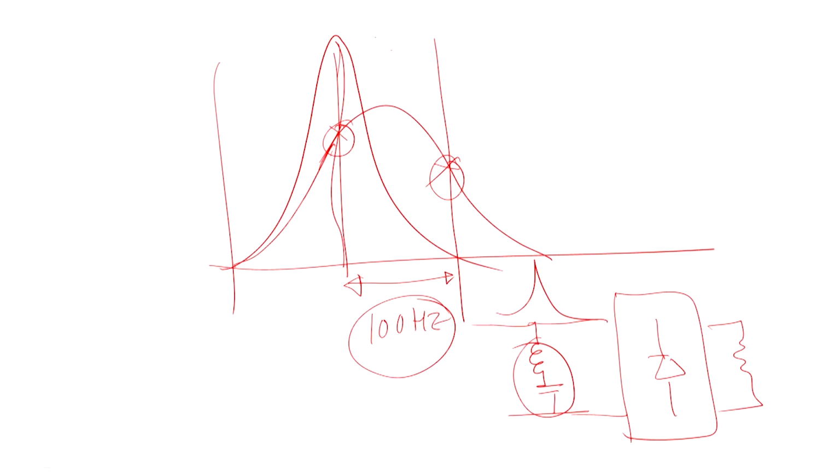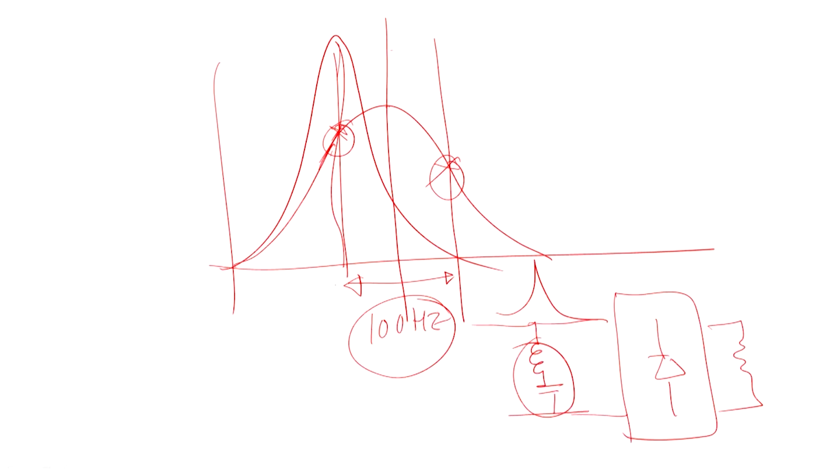But in that case you may tune to the fourth harmonic. So, peak may be fourth harmonic, but you can tune third and fifth both. So, then to some extent you mitigate the fifth harmonic as well as the third harmonic. Here your peak should be attenuated, and it is a notch kind of filter, and there will be a sharp cutoff for the third, and you can see that in the fifth the attenuation is not what you will accept.